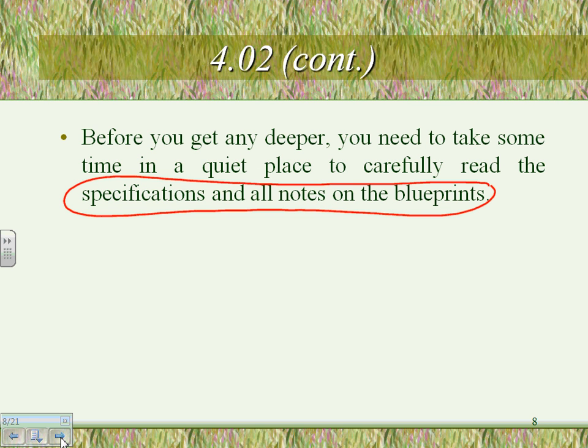As we start doing estimating with software, you're going to see a multiplier: you take off everything on 1 sheet and you multiply by 2. So if you made a mistake by accident, you took off 1 floor, and then there's a slot where you can put a 2. Now you multiplied your estimate for everything by 2 without knowing, if you don't know how to use the software. It's supposed to be 1, and accidentally you put 2. Now everything is multiplied by 2. Imagine how much higher your price is going to be. You're not going to get the job. So that's as bad as getting the job and not being able to get profit out of it, right?